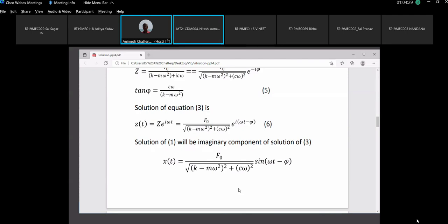So, as an engineer, what is the first thing we learned? That if damping is absent, never allow omega equal to omega n. And I can further say, never allow omega coming close to omega n. Not only omega equal to omega n is dangerous, even omega very close to omega n is also dangerous. So please remember, in forced vibration, is damping a villain or a friend?